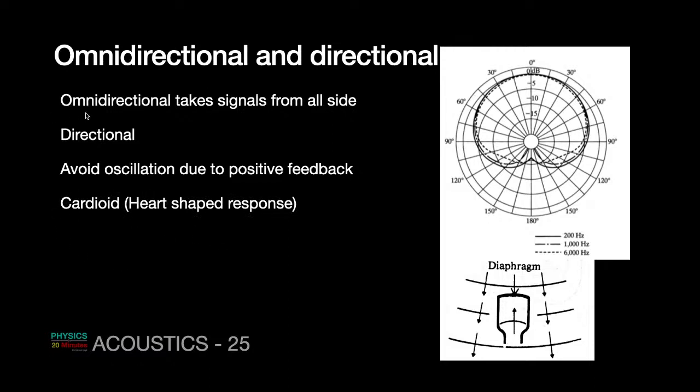Look at this drawing. For an omnidirectional the drawing is almost circular. It has a sensitivity in all possible directions. However, if it is directional, then it has more sensitivity in one direction, while you can see that the graph bends sharply in the other direction. So the sensitivity decreases. The radial distance from this circle describes the sensitivity.